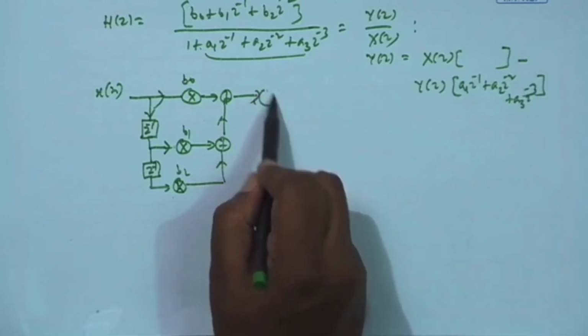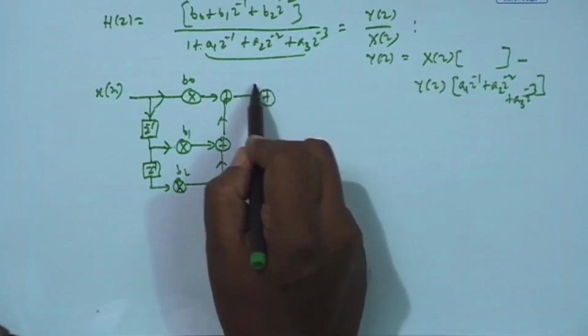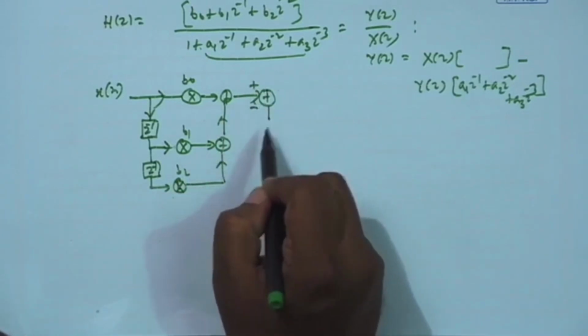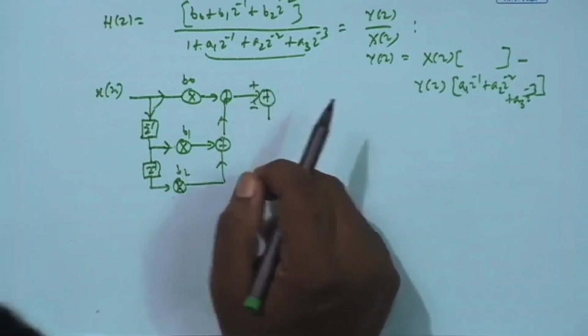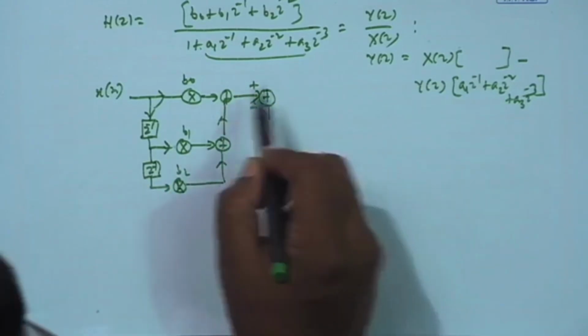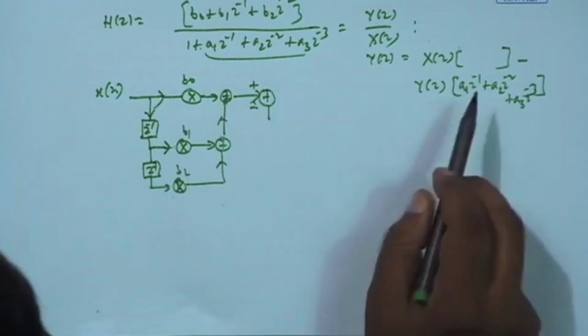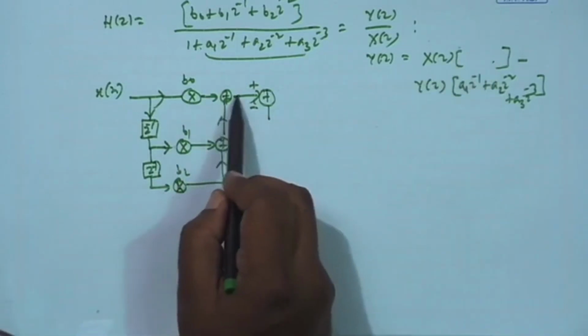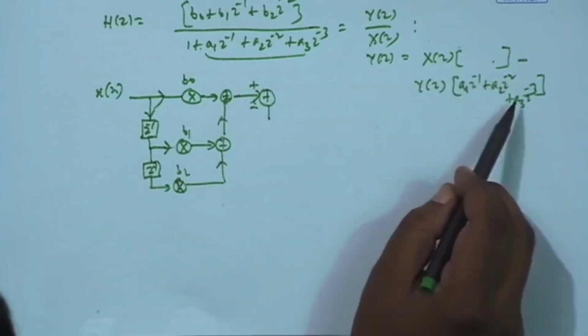So, from this I have to subtract. So, the adder becomes a subtractor actually, because how to do the subtraction? Take the 2's complement of the number being subtracted and then add. These are basic electronic stuff, I believe you all know that.